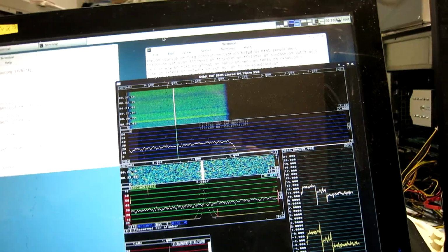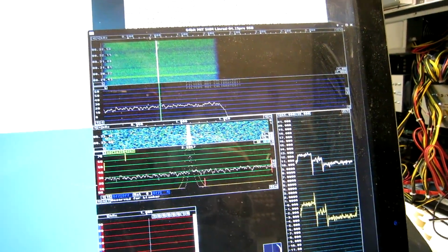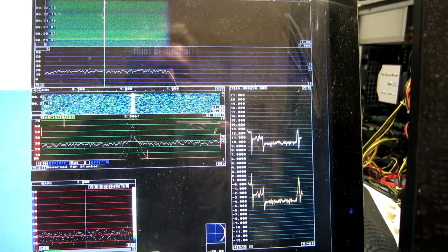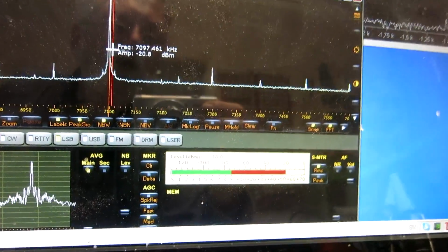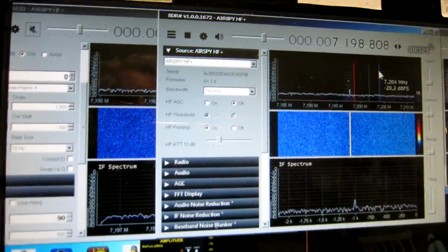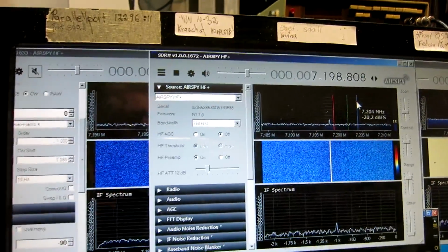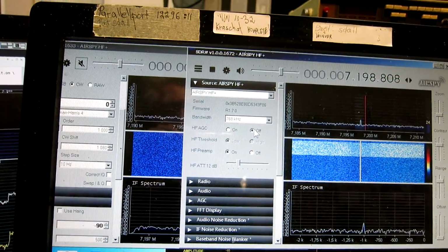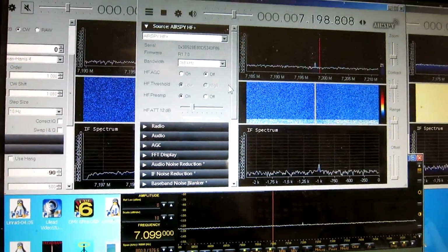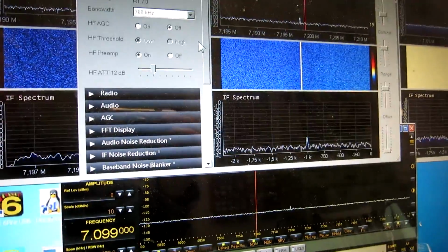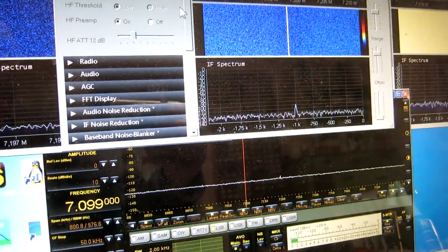So I have to switch it off and then on again to restore the loss I had before. And this happens at the level of minus 19 dBm. Now, this unit does not use AGC. I make sure that I clear the memory effects that it might have by doing that while having no signal, no strong signal present. And then I add the signal 100 kilohertz below in frequency.